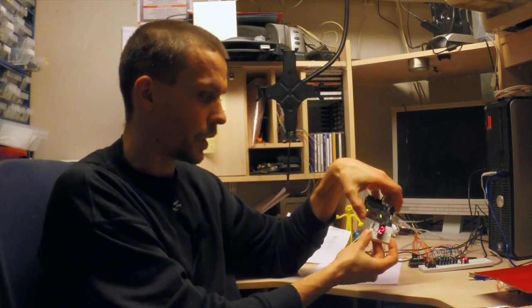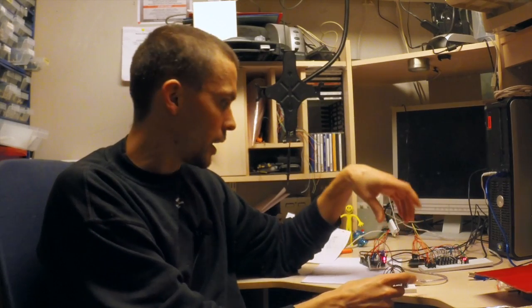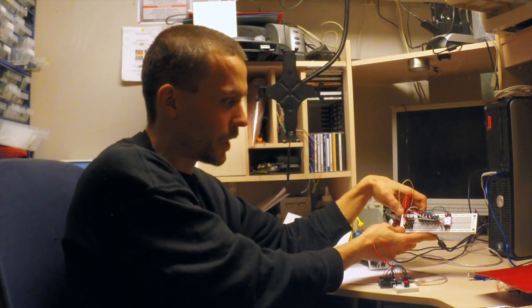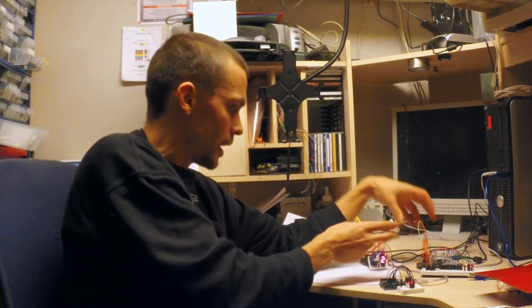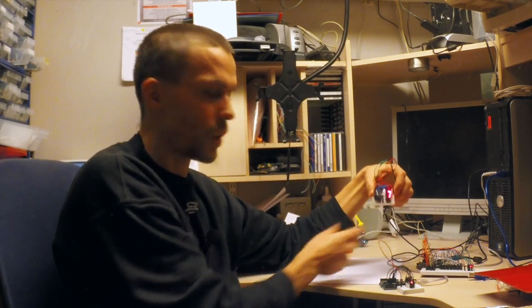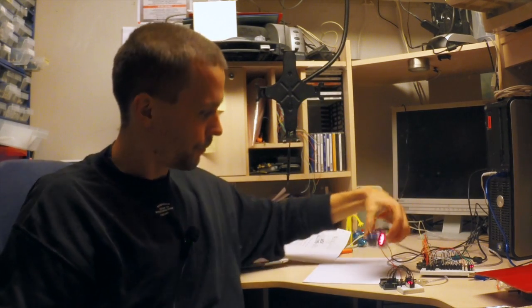In the first episode, this one, I'm going to show you how to hook it up directly to your Arduino, like this one here. Then we'll go through a dedicated 7-segment LED driver, the 4511, right here. And finally, we're going to look at the shift register, the 74HC595 here. And in each episode I'll also go through how to display the numbers 0 through 9.